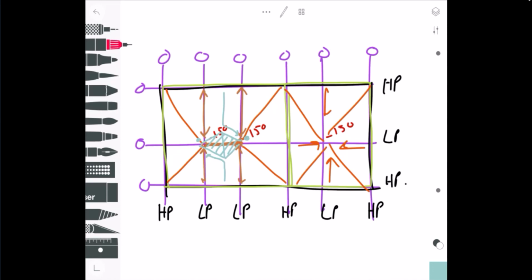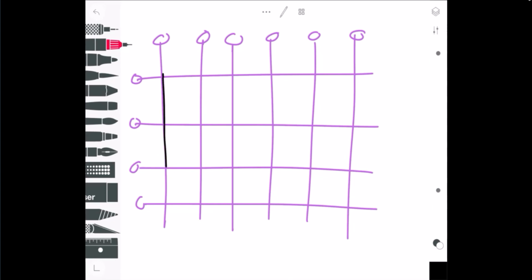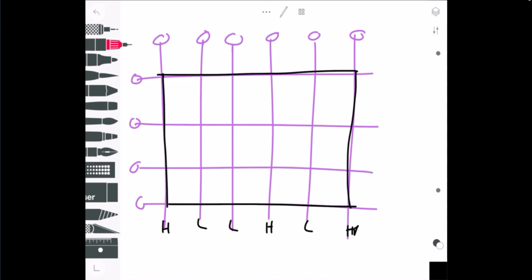Sometimes you'll end up with an entire grid bay that's flat, and you still just do a sloped insulation around it. I'll just sketch that out here. Okay, so here's a similar building, but I've added one more grid line in the horizontal. So now the roof is like this on this building, and I'll quickly draw in the high points. So again, high point, low, high, low, low, high. So same as last time. We're going to do two low points there to make sure that the exterior is on a high point.